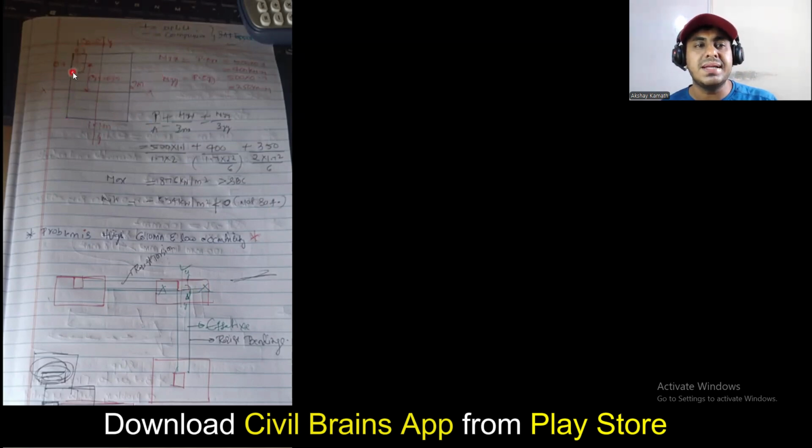So here what is happening, the eccentricity is in both directions, right? If you observe it carefully, you see here the eccentricity is in both directions. That means your column is here, the center of the footing is here. So from here to here also there is eccentricity. This is an eccentricity in the xx direction, and here also you have an eccentricity like this. So this is eccentricity in your yy direction. This is eccentricity along xx direction. This is eccentricity along yy direction. So from both sides there is eccentricity.